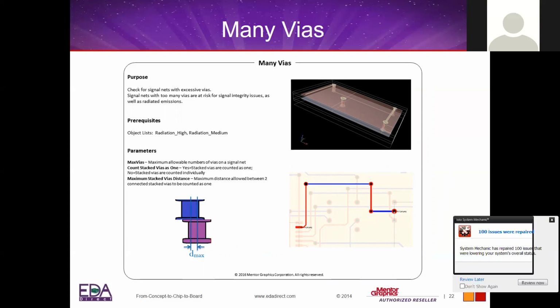Well, the constraint might be, hey, I'm still keeping the length of the address bit to be within 2 inches or 1 inch. I'm keeping the length. So why does that matter? Well, it does, because every via structure that the signal has to go through creates discontinuity, crosstalk issues, reflections, all that. So checking the number of vias is important.